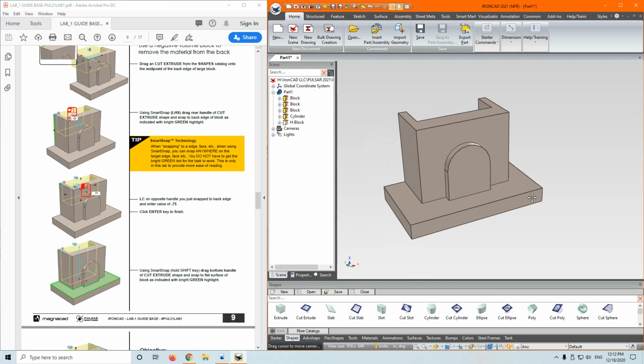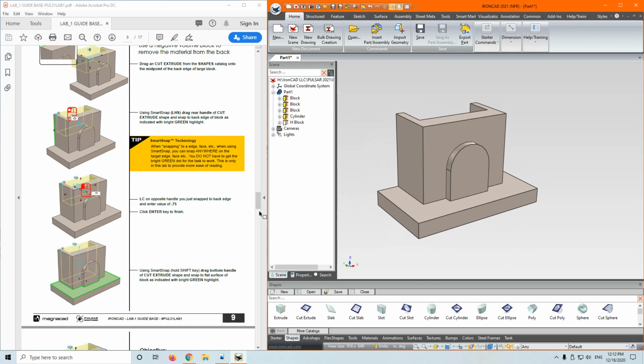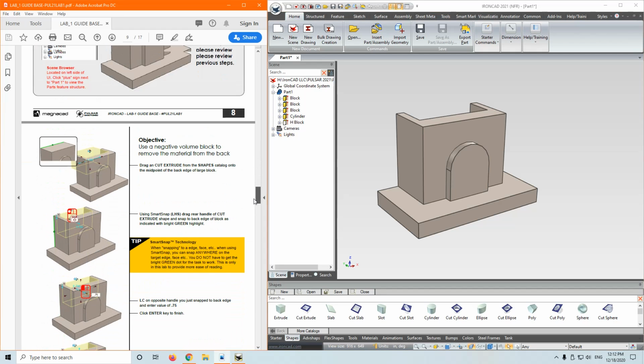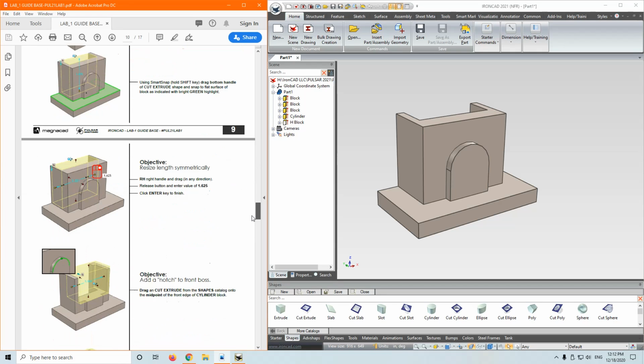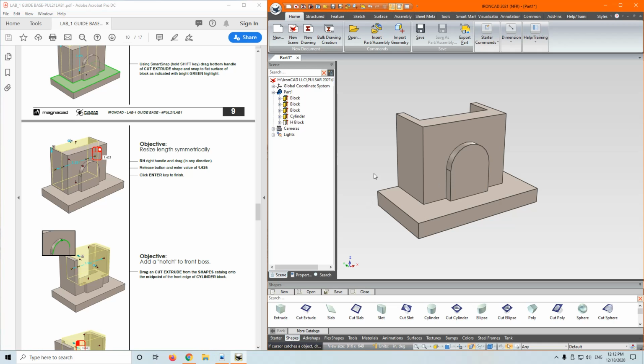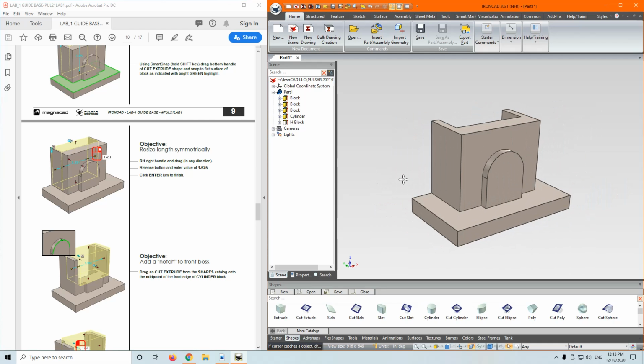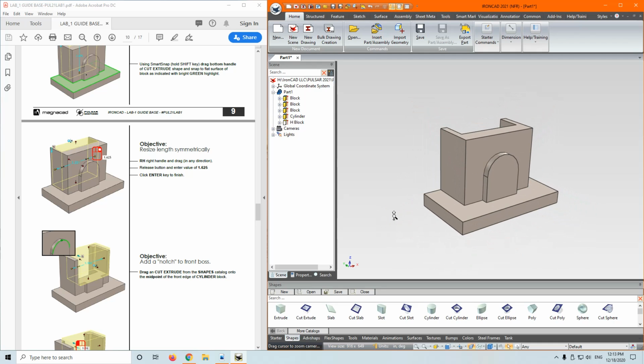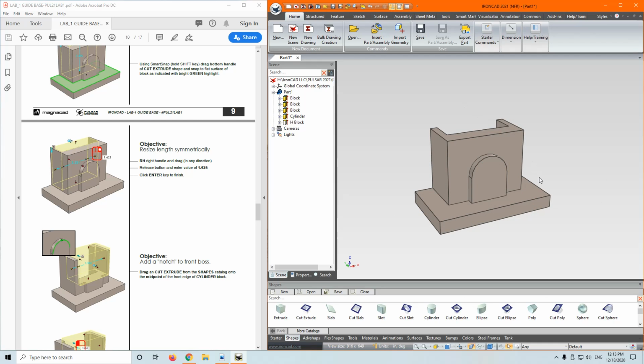You should probably update the view sensitivity in the modeling portion, but it also works that way. And a quick tutorial on the middle mouse button: middle mouse button down with the shift key is a pan, with the control key is a zoom, and without any key is a rotate. Quick lesson there.